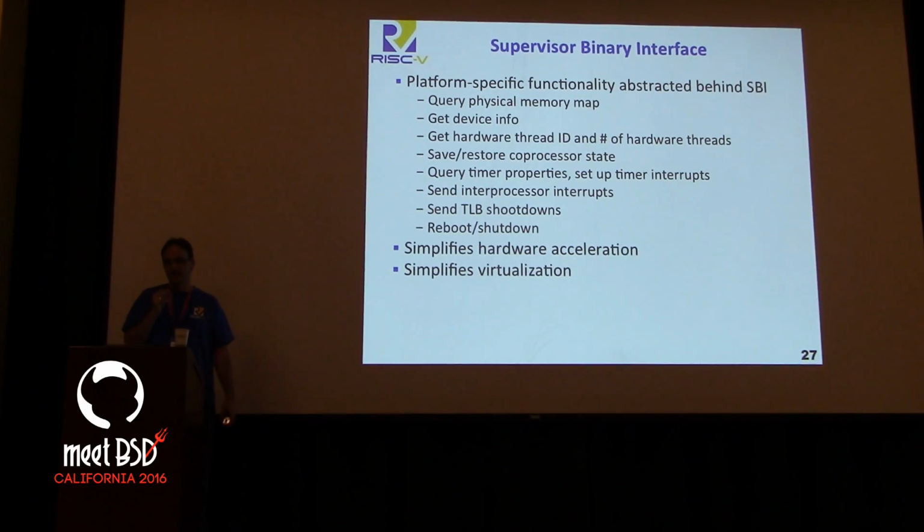So the SBI covers a lot of things that might be done with registers or special instructions. We're trying to abstract them into an SBI to give the hardware more flexibility in how it's done. And one thing, if you're really corrupted by how bad x86 is at taking system calls or context switches, those numbers, how long it takes that thing to do that, you shouldn't use that to worry about these context switches. These can be much faster than current x86, because we don't have all that baggage to implement this stuff, and we hope we can get a cleaner interface there.